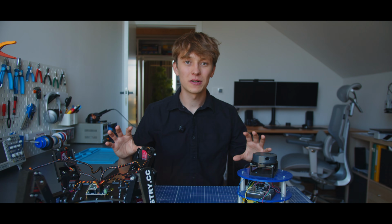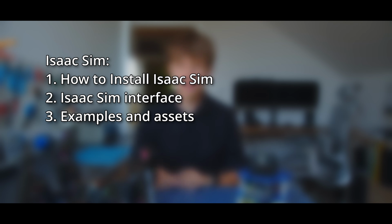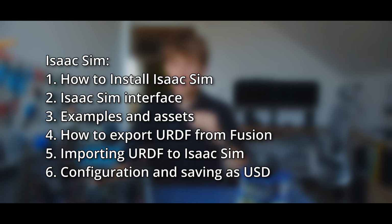I will add chapters to make it easier to navigate. We'll go through how to install Isaac Sim, the interface, how to use the examples and built-in assets. I will show you how to export the URDF of your robot from Fusion and bring it to Isaac Sim, how to set all the settings and save it as USD, Universal Scene Description file.